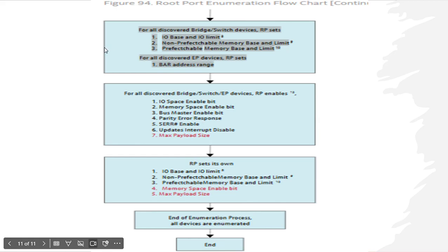After configuring all the devices, our processor will send the config packet, it will issue the instruction to the host bridge. The host bridge will insert the config transactions. Yeah, this is the enumeration process.